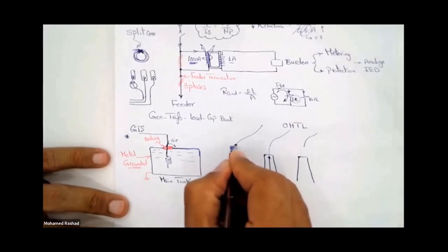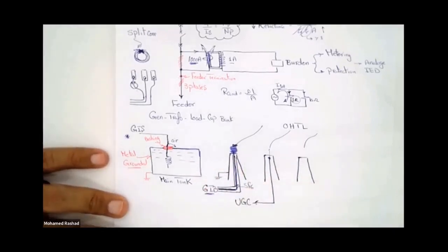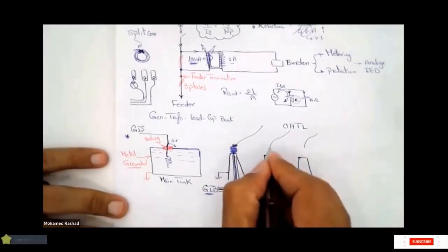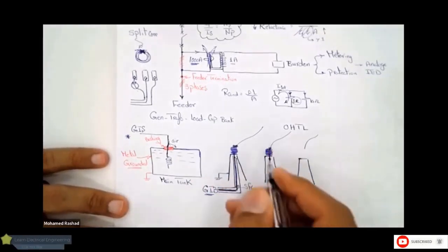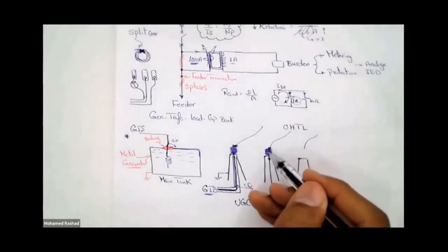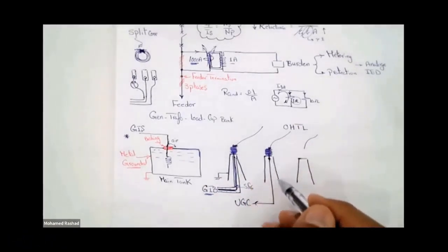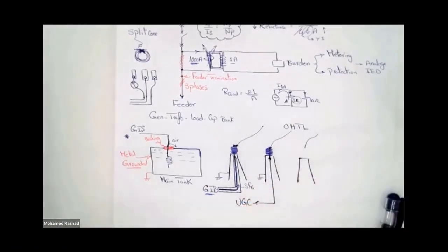Here you have the conductor terminal, and it is connected from inside here to your conductor, whether it's a cable or something else. It is designed in such a way that it provides insulation between the current carrying conductor and the non-current carrying part, which, as I mentioned, is grounded. Beautiful, very nice function. This is what we refer to as the bushing.